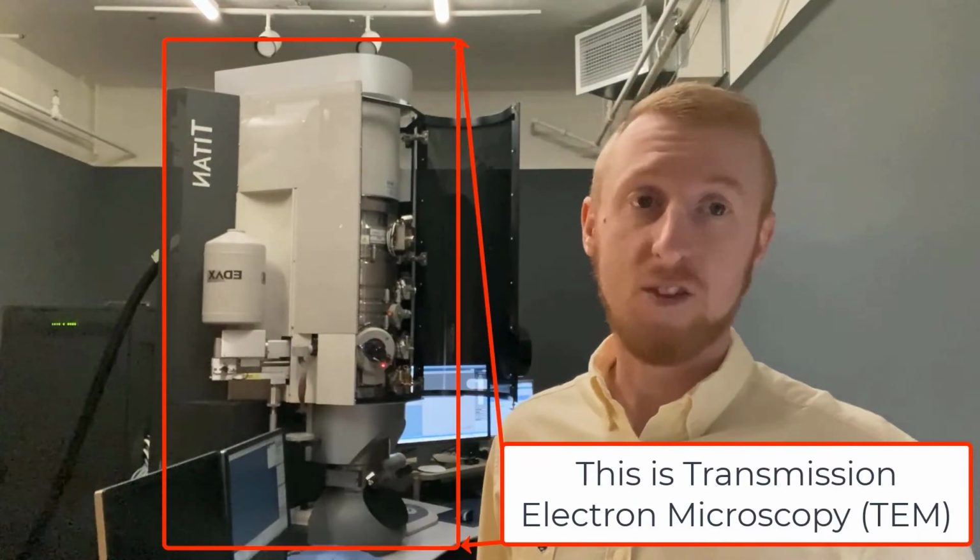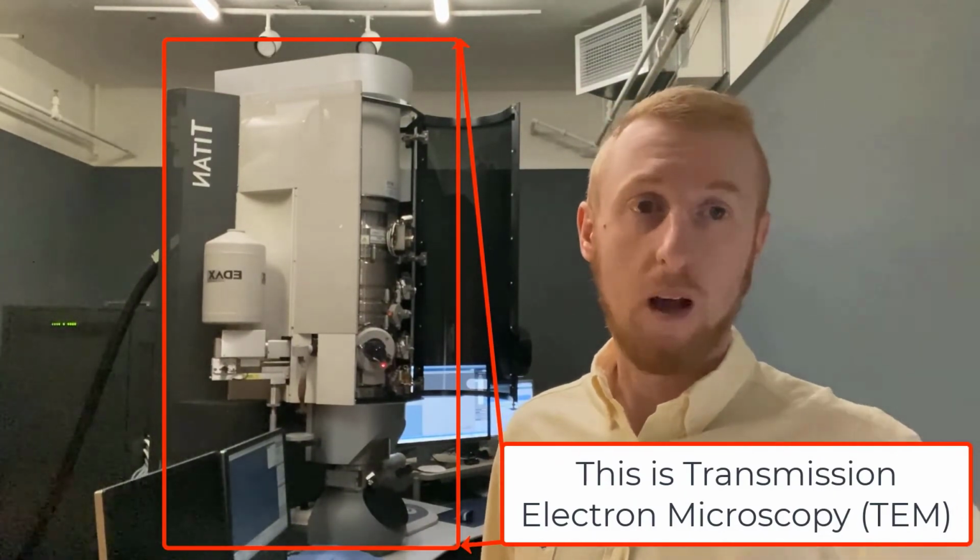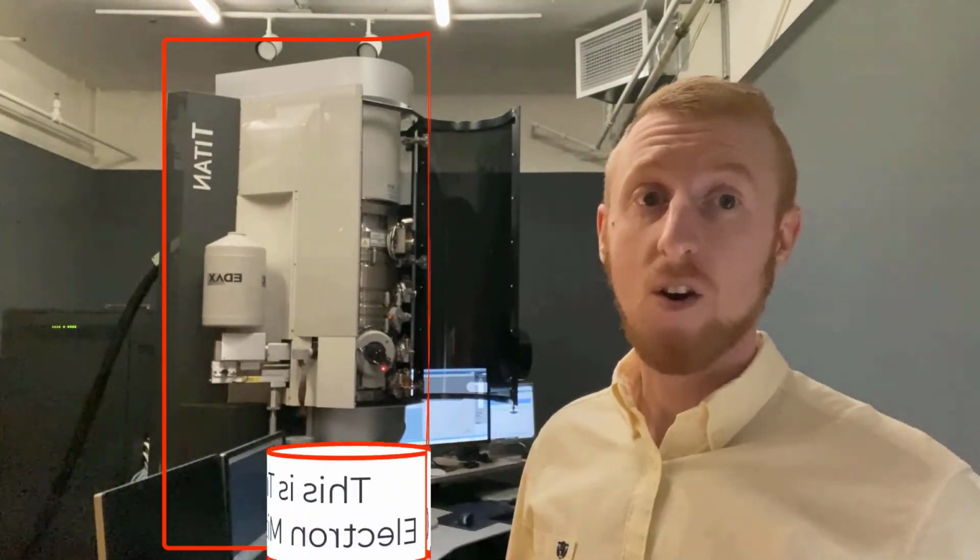We are in the transmission electron microscope lab. To take images or video of the metal surface at high resolution at micro or nanoscale, the electron gun located at the top of the microscope must emit electrons down through the microscope. The emitted electrons transit our metallic sample, that is in the liquid, and give us a two-dimensional image of the density distribution of the transmitted electron beam.